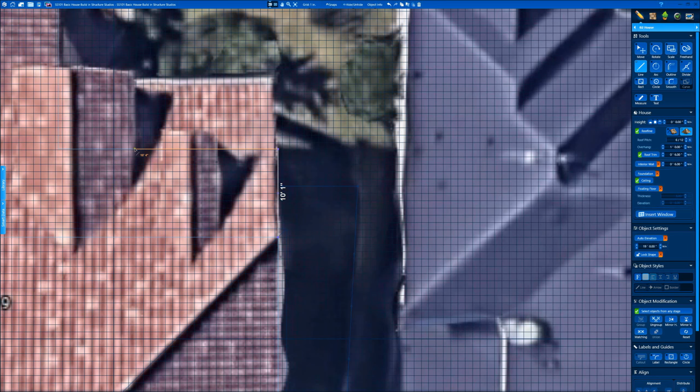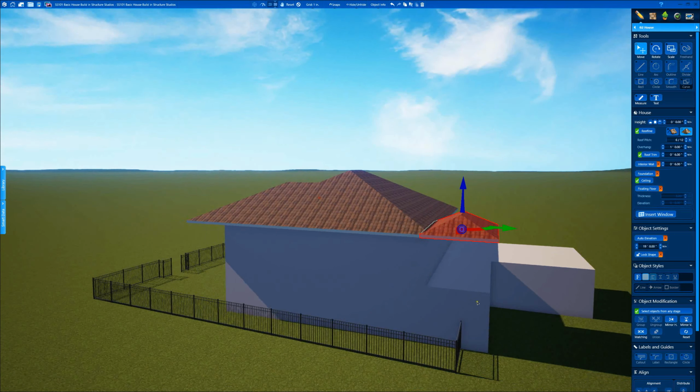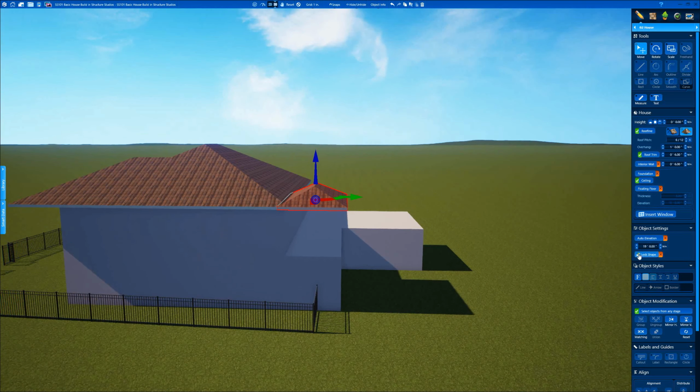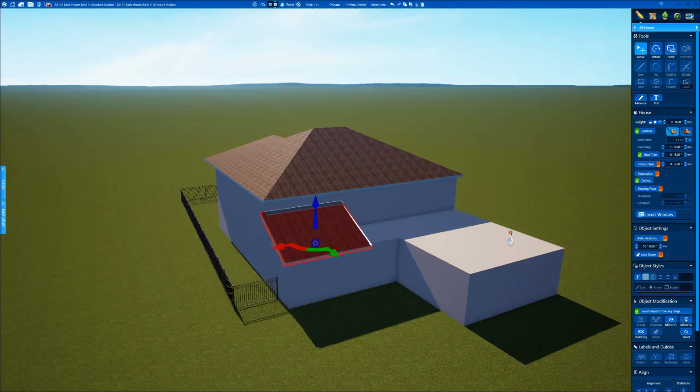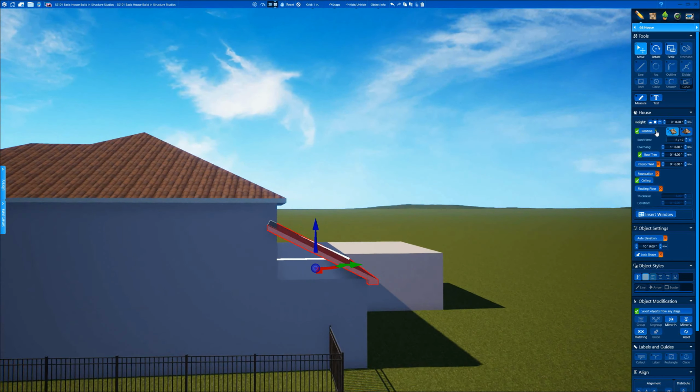Click, we're going to come over and relative angle is on. Click, click, finish it up, and that's going to be our shed section. It's going to drop down to this lower section of the front porch. So roof only, turn it to gable, gable, gable, 3 sides. We have this empty, so we add 1 to it, and it's going to add this. But it's not going to work because our soffits and our overhangs need to touch